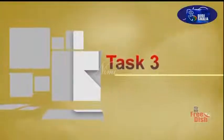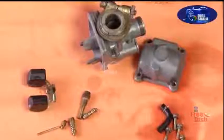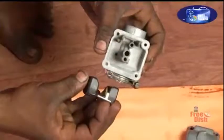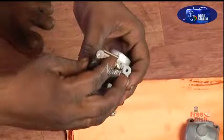Task 3. Assemble the parts of the carburetor. Assemble the components one by one in the reverse order. Check the float. Connect the float.